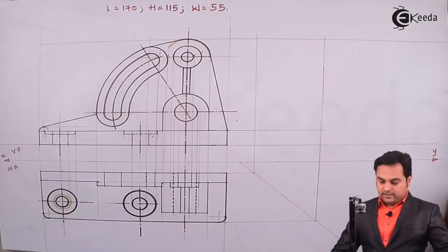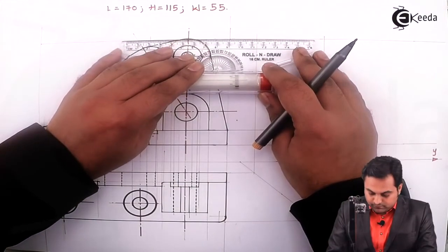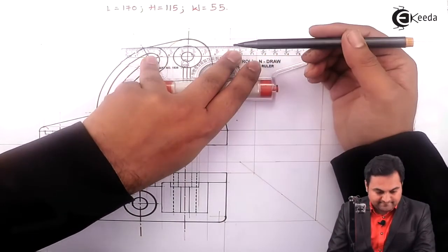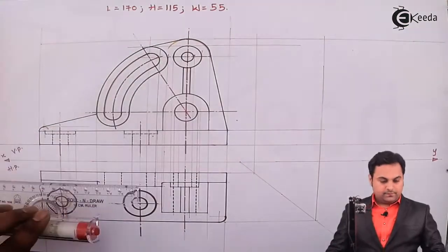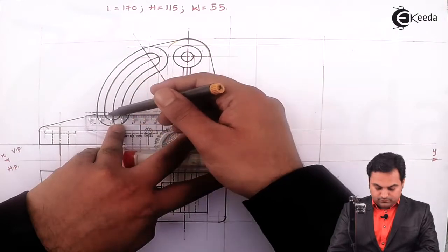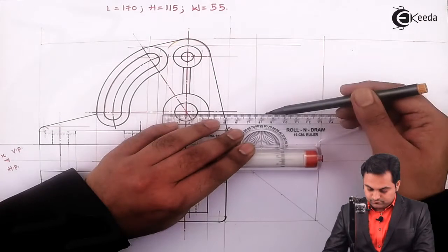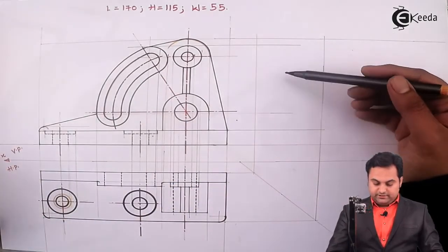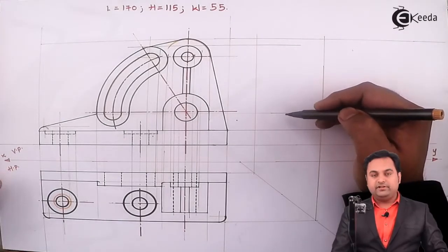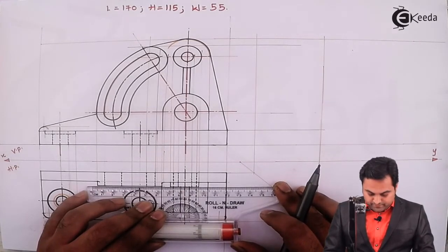So for that I need the height from the front view, projecting them light. So this is the height within which the object will be having a width of 15 mm. So that width I'll get from the top view of 15 mm.